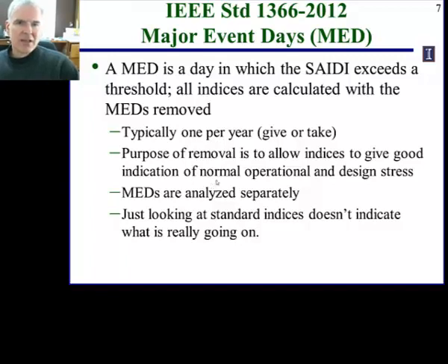Okay, however, in calculating these indices, the IEEE standard defines something called a major event day, MED. The major event day is a day in which this SAIDI index exceeds a threshold, and then all the indices are calculated with the major event days removed. So this might correspond to something such as a large ice storm, or perhaps a hurricane, or a tornado that is causing a large number of customers to be outaged.